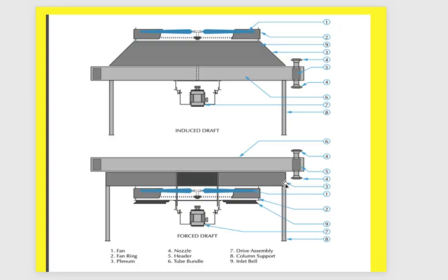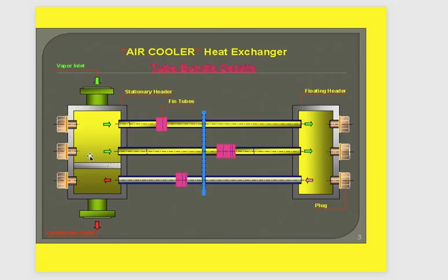Okay, a header box. You have many types of header box. Header box working with plugs, header box completely covered, many types of header box to distribute the process fluid into and out of the tube itself. The header box can be clear in this shape. This is a plugged header box, and you have here inlet liquid or fluid, okay, going through this tube and returning back through the other tube here, and this is the header box.